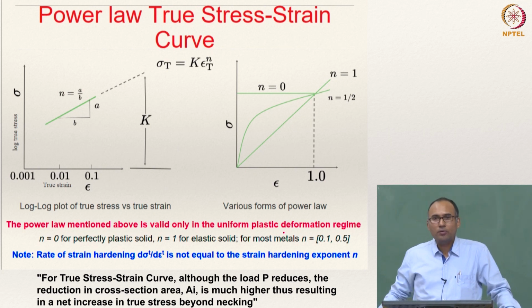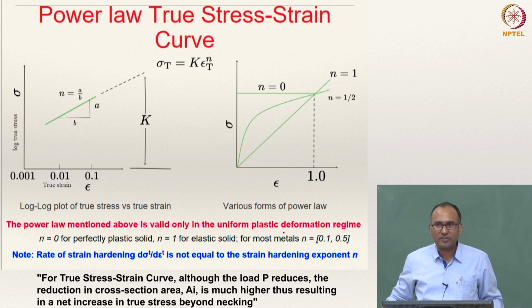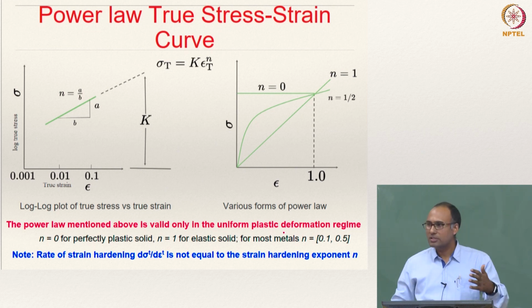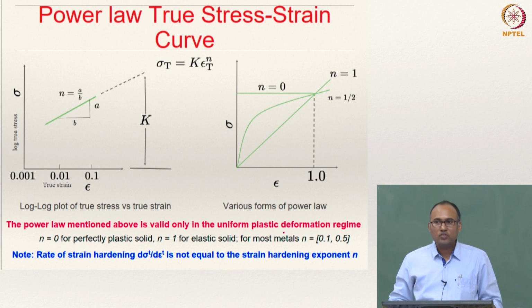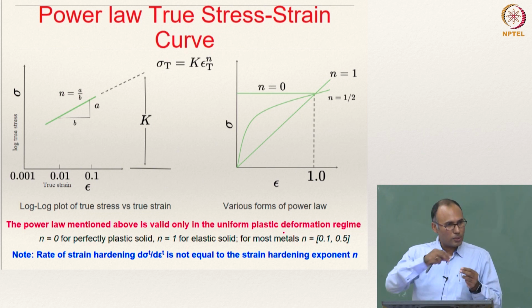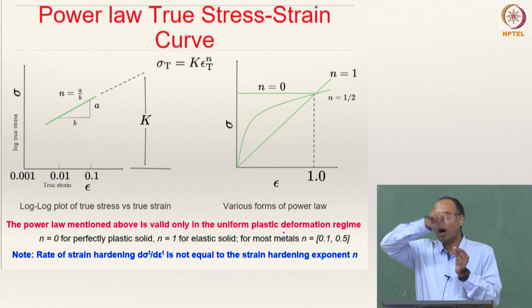All right. So now we have defined the first region, which is called the linear elastic regime. So we have a formula for that, that is represented by Hooke's law, right. It is named after Robert Hooke, the English engineer or physicist who understood the elastic deformation of materials, who did seminal experiments in understanding the mechanical behavior of the material, right. So, sigma equal to E times epsilon is the formula that we use to represent the linear elastic part of the system.